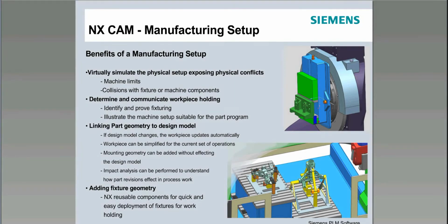Inside the manufacturing setup, NX provides the ability to link the design model to the manufacturing workpiece such that you can simplify the workpiece suitable for your machining processes in the setup, such as removing holes from the part or slots and exposing nice clean surfaces for surface machining.